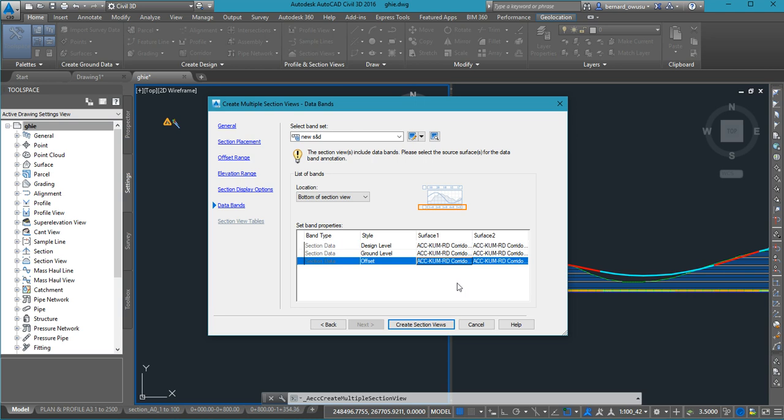It's what? Because you have EGL and what? Okay, so that is what you selected. I've updated this template. I don't know if I did it in the old one, the one we are using. But I'm saying that for the first one, select the Kumasi corridor, and for surface 2, select the EGL or DTM, whatever yours is. Surface 2 is the DTM or EGL. If it comes and there's a problem, we'll reverse it.